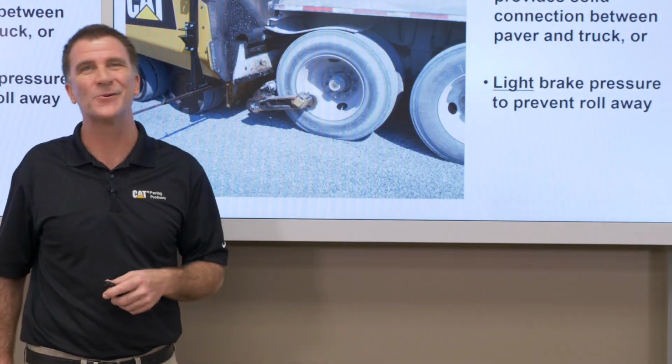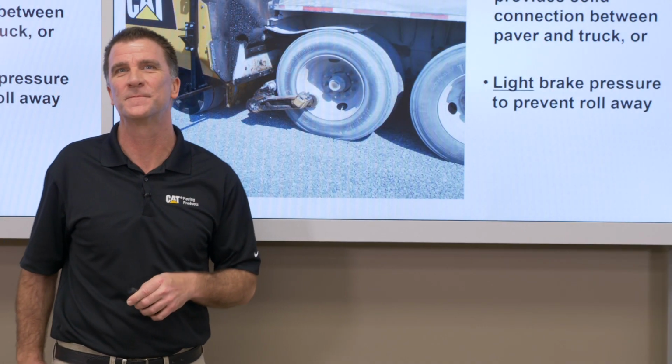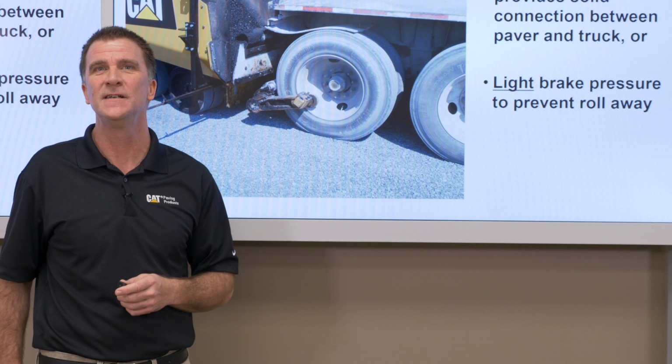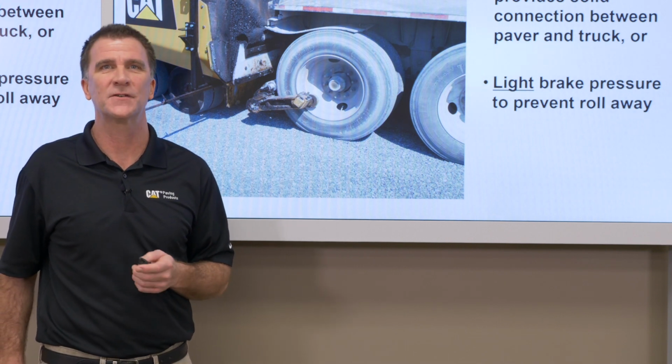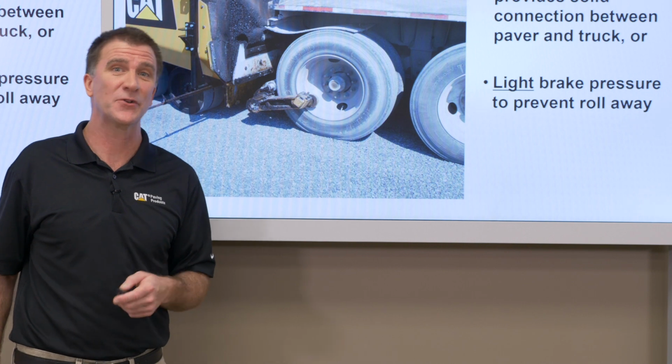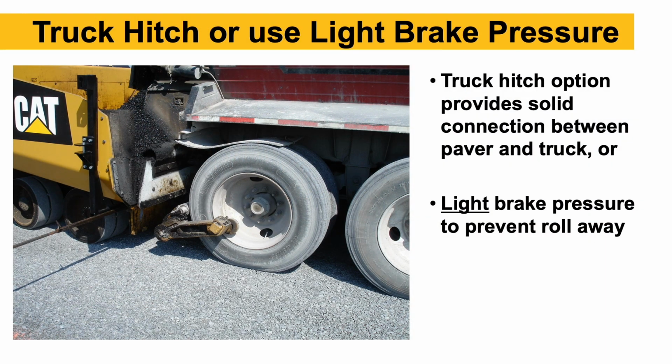A lot of drivers don't like truck hitches because they scratch their rims and things like that. They're not always necessary. I see a lot of successful paving operations that don't use truck hitches, but you have to train the drivers to use light brake pressure so that truck won't roll away from the paver while it's transferring the load from the truck into the hopper.